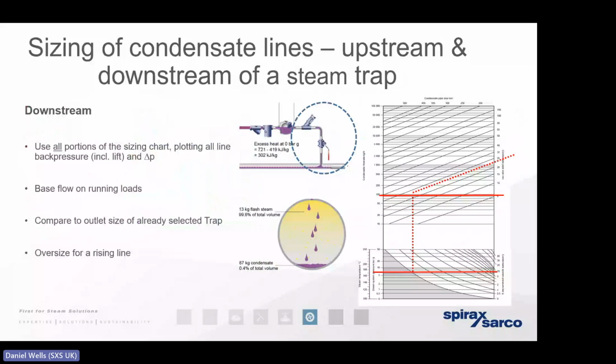If that pipework were undersized, the steam trap could be sized perfectly correctly, but that expansion would have nowhere to go. It would expand, and unfortunately, that expansion would result in the condensate being held back and flooding the heat exchanger. The rate of heat exchange would extend significantly.